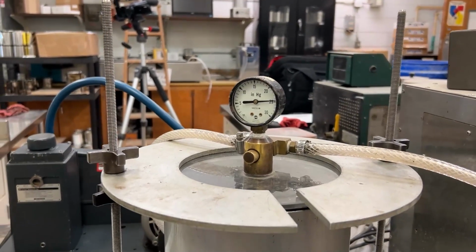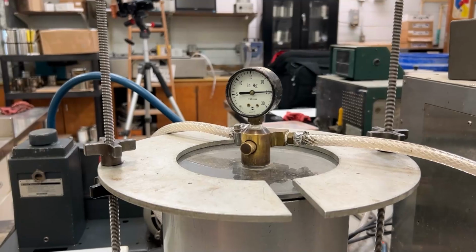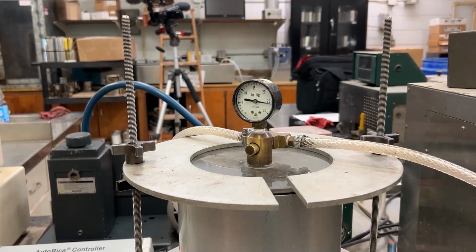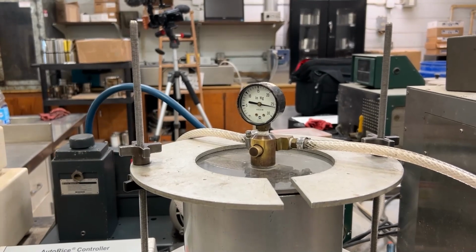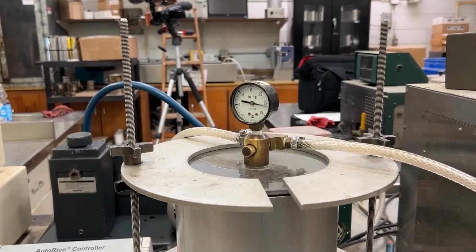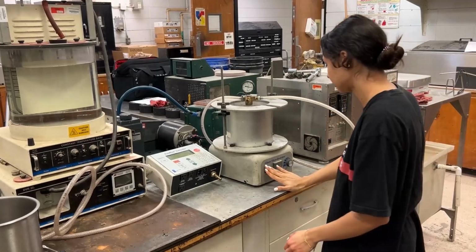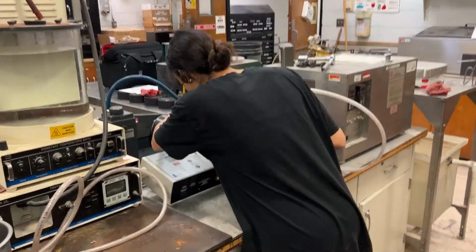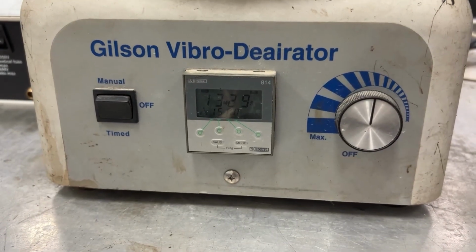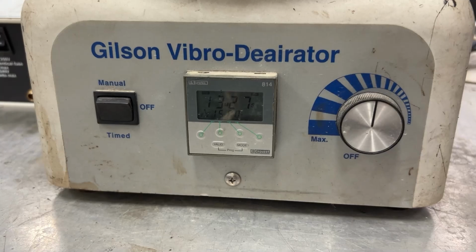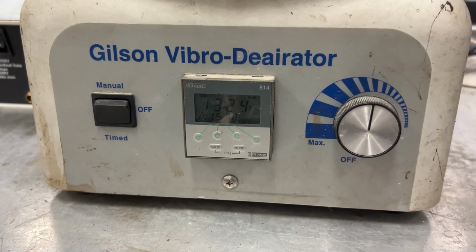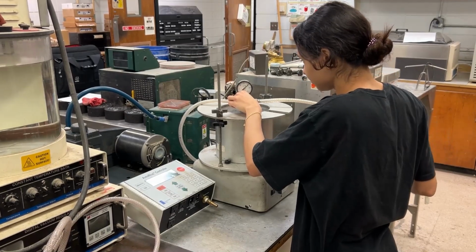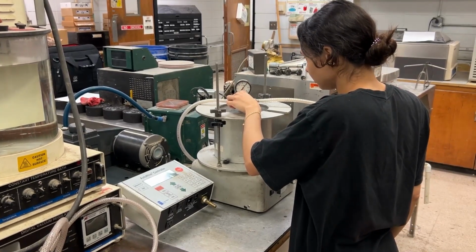Make sure your bleeder valve is closed before you start the vacuum pump. Check the pressure gauge to make sure it is moving toward 30 plus or minus 5 millimeters of mercury. Once you are below 30 millimeters of mercury, turn on the vibrating table, initiating a vacuum period of 15 plus or minus 1 minute. Set a timer if needed. At the end of our 15 plus or minus 1 minute vacuum period, release the vacuum through the bleeder valve by increasing the pressure at a rate not to exceed 60 millimeters of mercury per second.